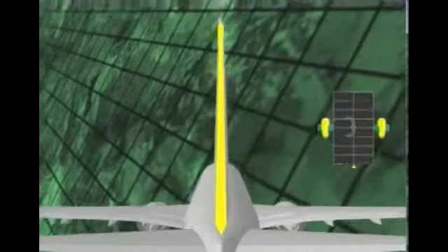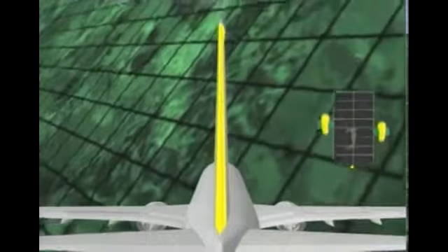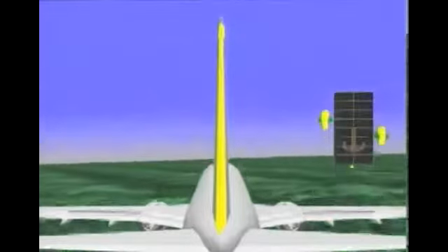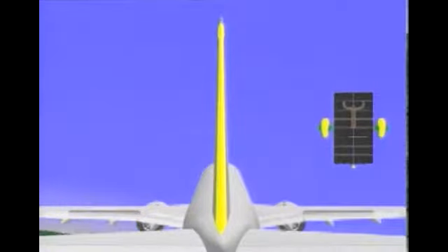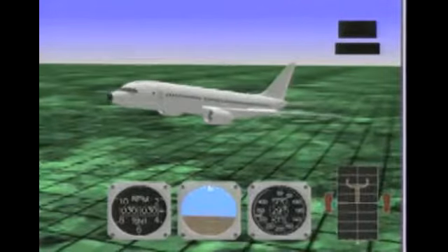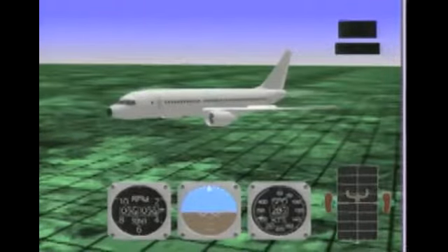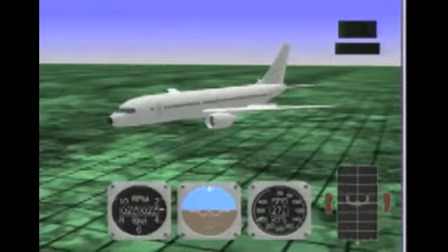If full lateral control application is not satisfactory, you may need to apply rudder in the direction of the desired roll. As the wings approach level, use the procedures we discussed earlier for a nose-low situation. Adjust thrust and drag devices as required.